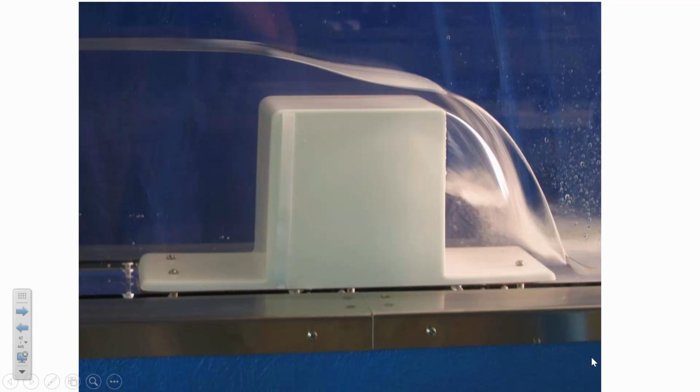So what we're going to do is go down into the lab and observe flow over an obstruction similar to this. What you can see is that the water surface draws down a little bit as it accelerates over the obstruction, and then there's additional drawdown as the water goes over the edge. And so it's a little bit tricky saying exactly at what point over this obstruction you're seeing critical flow. And that's one of the things that I hope we can nail down today: we'll do an experimental comparison of the theoretically predicted critical flow for a certain flow rate and what we observe on the Broad-Crested Weir.